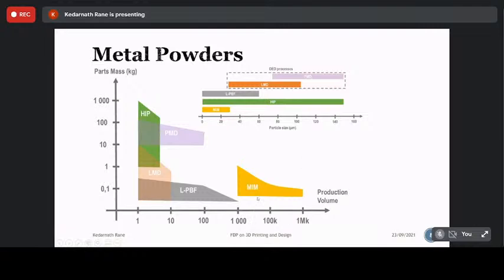When it comes to the use of metal injection molding, you need to consider the cost of post processing as well as the tooling cost, because the tooling is like plastic injection molding, where we are going to produce millions of parts. Similarly, we consider metal injection molding viable for parts which are required in thousands, unlike other processes like laser powder bed fusion, LMD or HIP.